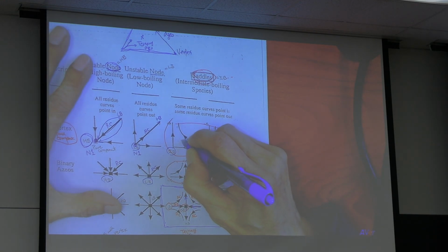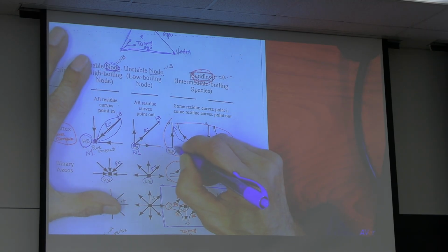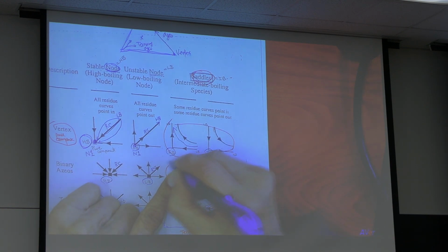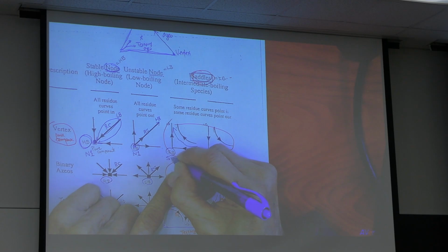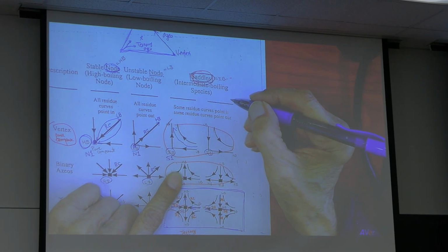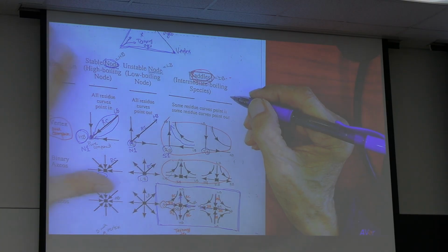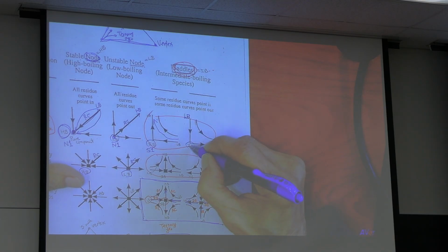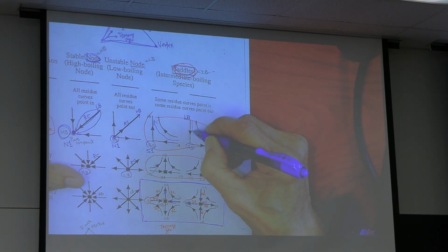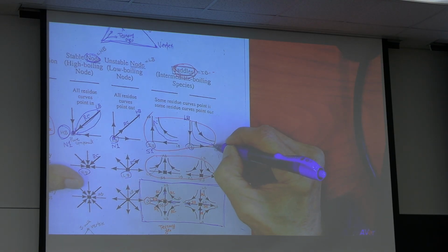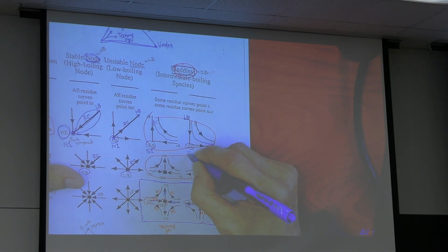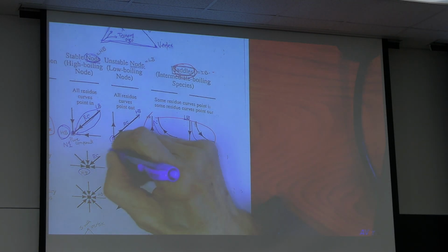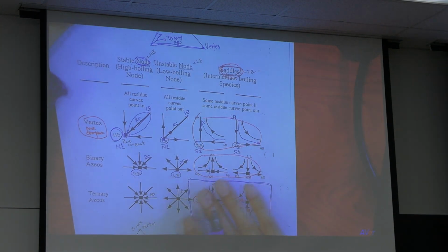So your RC goes that way, bypass intermediate component. We call this saddle with 1 component, S1. The other way is low boiling, intermediate boiling, high boiling. Your RC goes this way. This is also a saddle with 1 component. 1 refers to pure component.